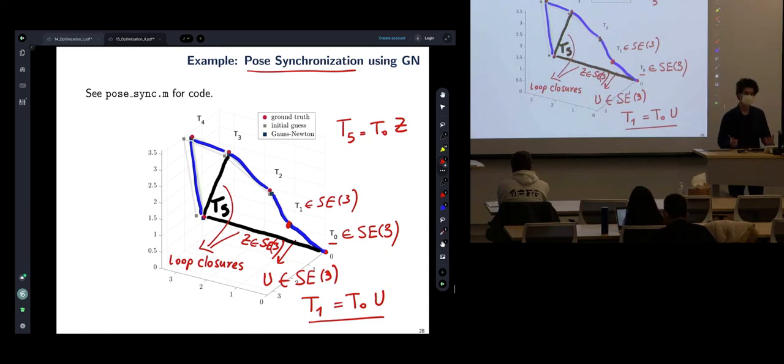It's not going to be perfect. The image processing part, registration part, and tracking part in the front end. Necessarily, in practice, you might add some outliers. Once you construct the graph, this is just an optimization problem that we talk about. That's the back end of the SLAM. So current SLAM paradigm is front end, back end. Front end is the messy part that processes all the raw data to build this graph. Once you know the graph, it is very principled. You just solve an optimization problem.